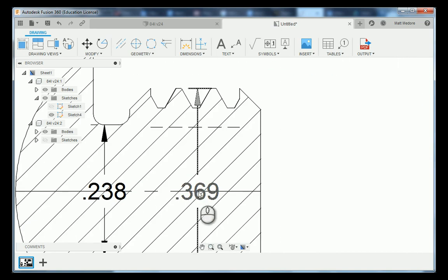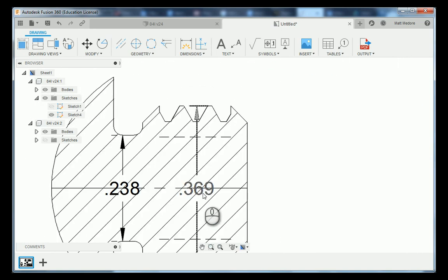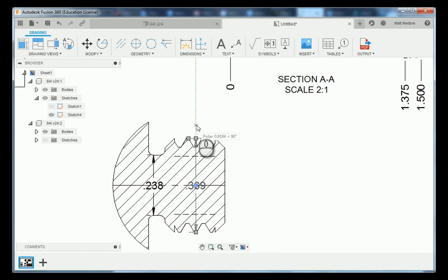After I land these measurements, I'm going to get these measurements off of my part. I'm going to left click on them and then choose that little square in the center, and that will give us the ability to put an extension line in. I'm going to repeat that on this other one. Like so.